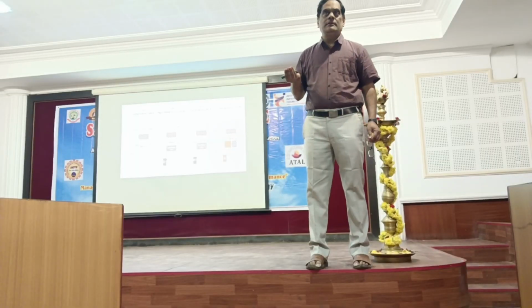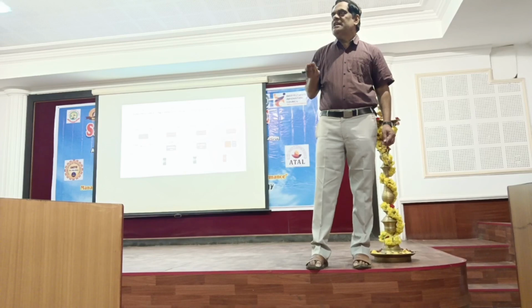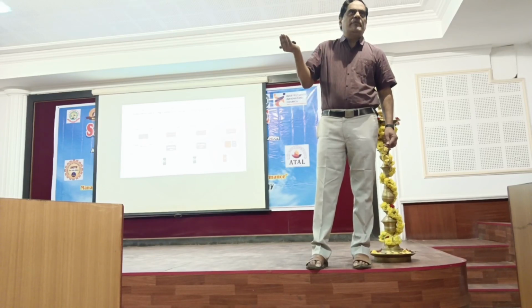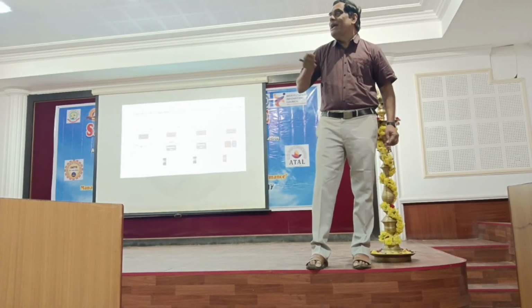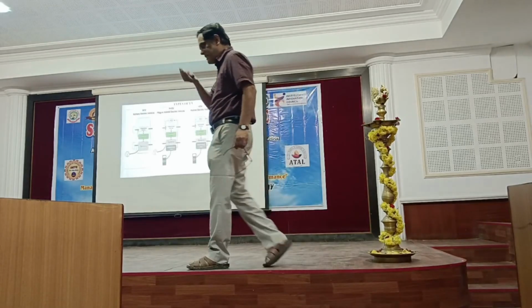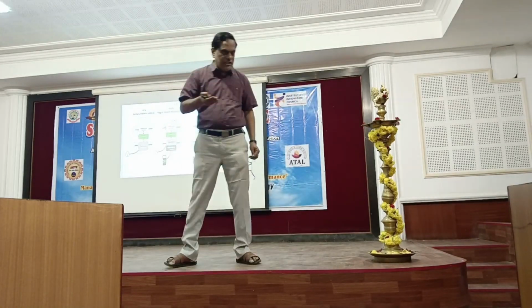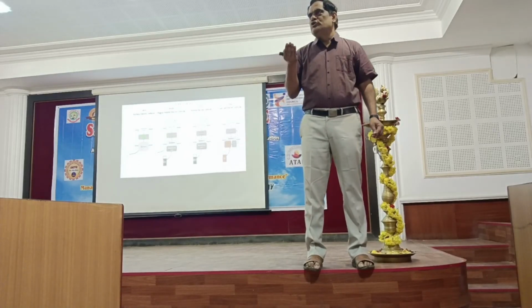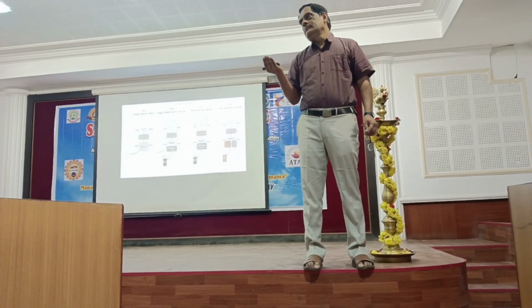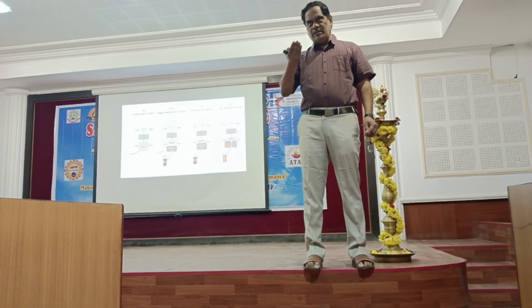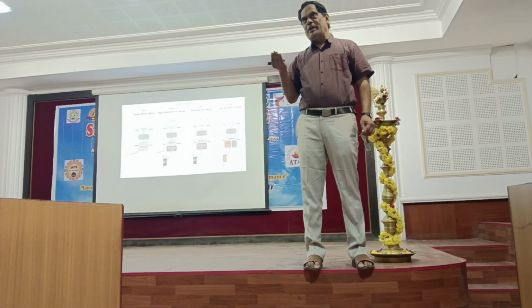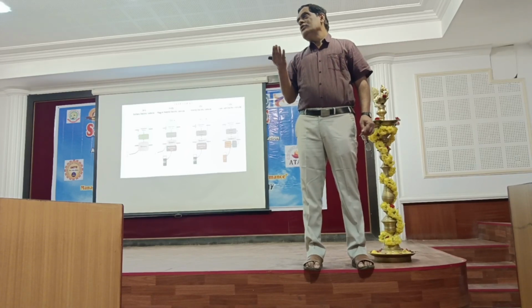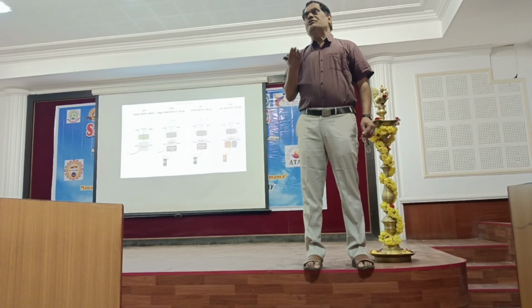You know about OCV? Each lithium ion cell chemistry has its own OCV. What is OCV, by the way? You already know. When you develop a new cell, you have to establish a cell chemistry. Of course, you know what output voltage it can give. For that, you should know the open circuit voltage. It should be almost close to the theoretical voltage. From electrochemical principles, for a given cathode and anode material, I already know what voltage it can give, actually. Open circuit voltage.